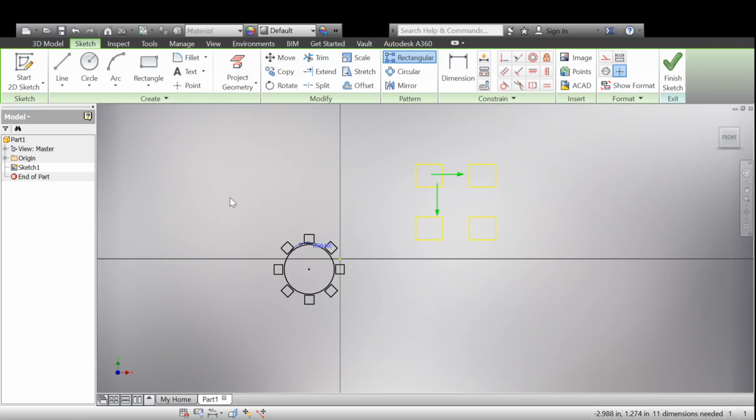So I can say that I want like a 5x2 grid, and there's 5x2 of that, and I can increase the spacing horizontally to say 2 inches instead, and then I can increase the spacing vertically to whatever I want, say it's like 3 inches vertically, it gaps there. So these dimensions here, this dimension is the spacing here, this is the vertical spacing, and then the 5 is the number of repetitions we have, or number of columns, and then the 2 was the number of rows.